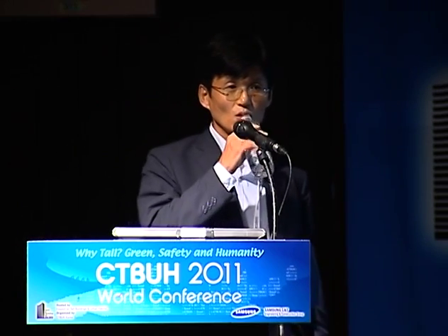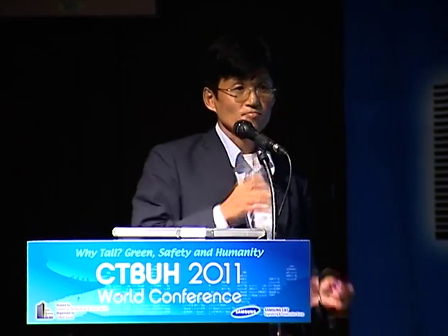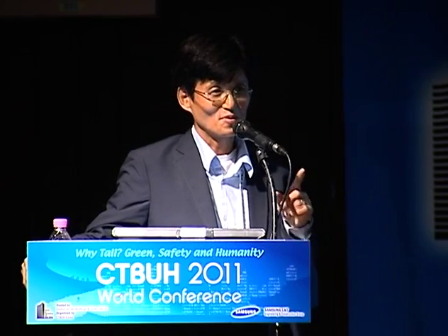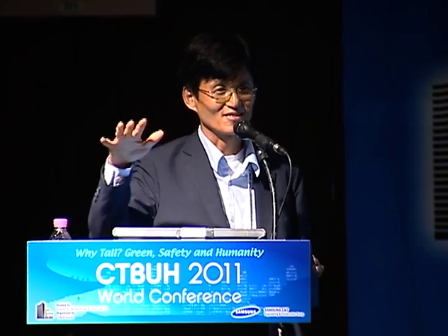Okay, one more question there. So you check the crosswind displacement for the tilted and also the helicopter type. Yeah, but these are only for along wind, only for the static response. The dynamic response, as you were probably asking, the crosswind direction, is not considered.